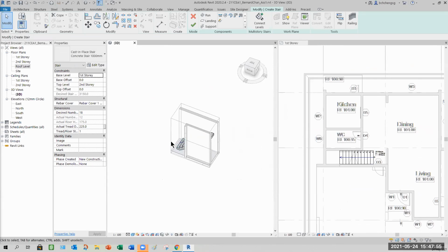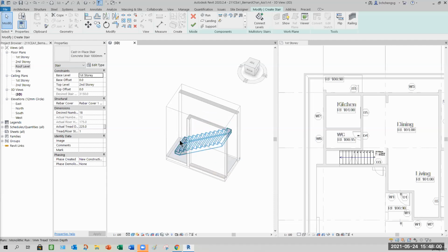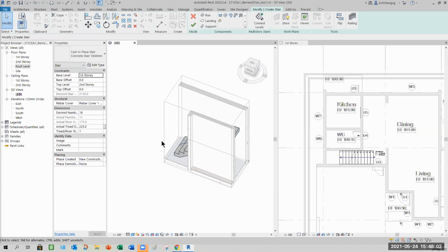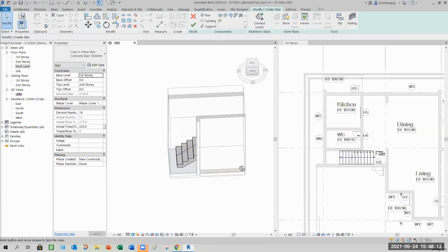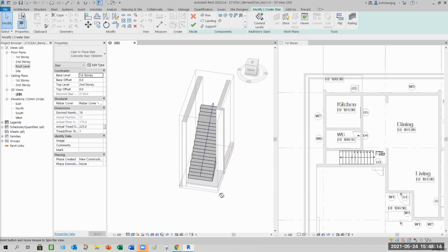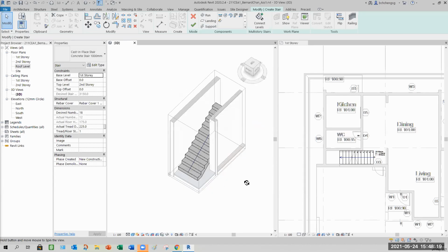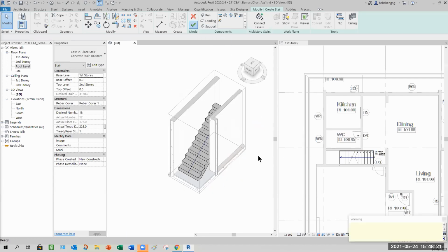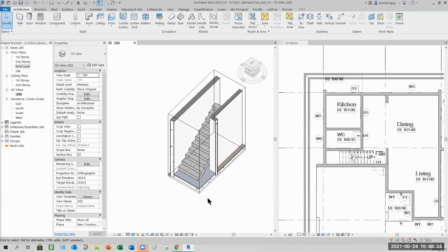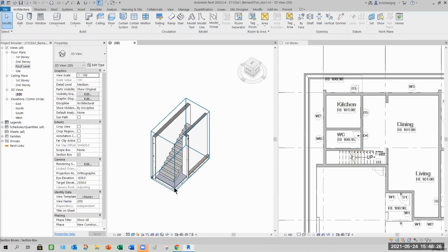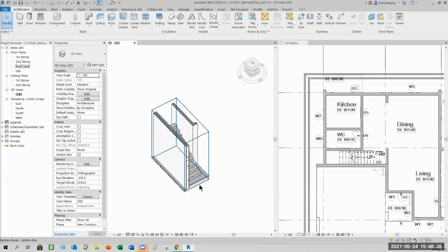So you may need to resize a bit. Cannot select. Why? What's happening? I must finish first, right? Because here there's a wall. Click finish first temporarily. Don't worry about the error because it detects that the staircase has not reached the right levels.